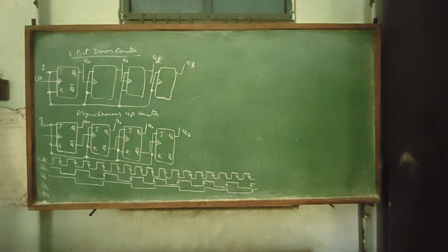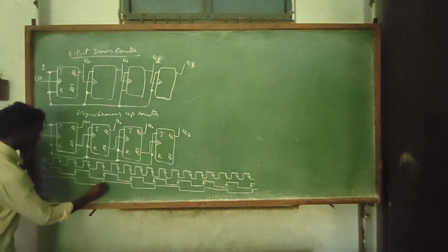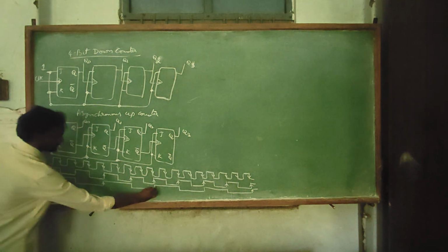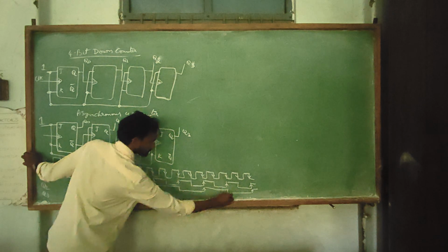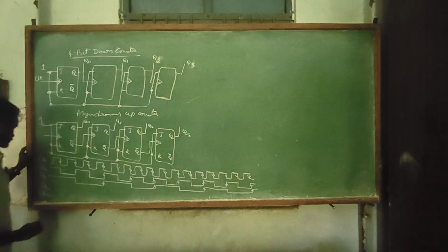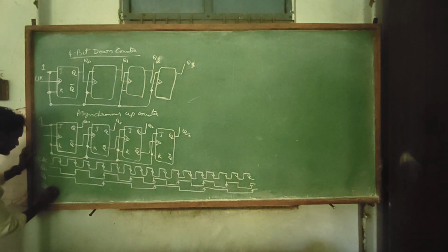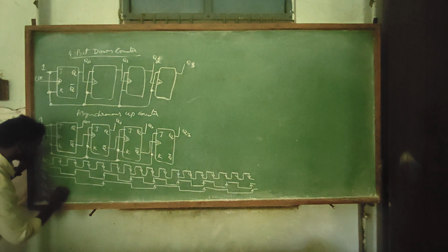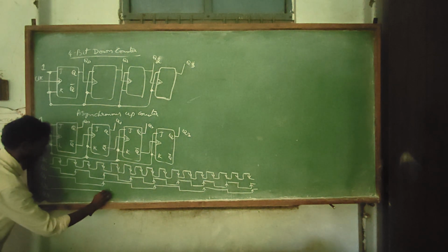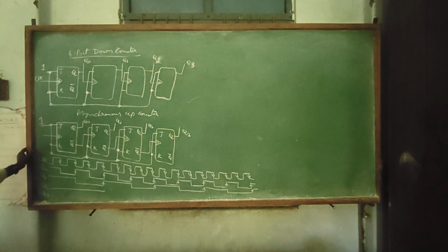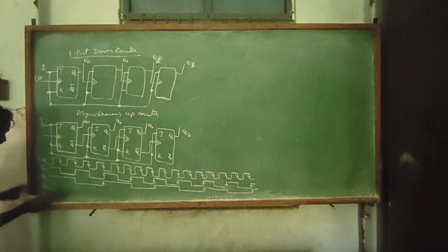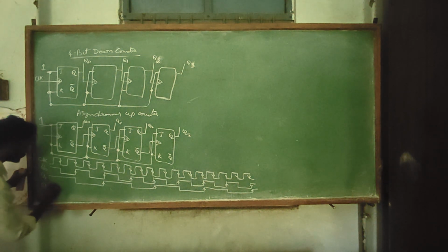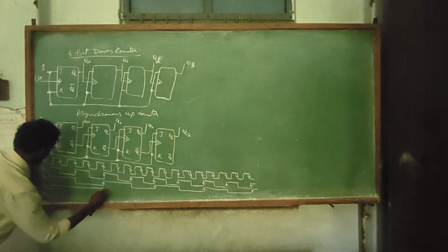Here also for the next level we have to see the rising edge. So Q2 changes sign at the rising edge of Q1. Q2 is already at high initially, and that goes to 0 at the rising edge of Q1.